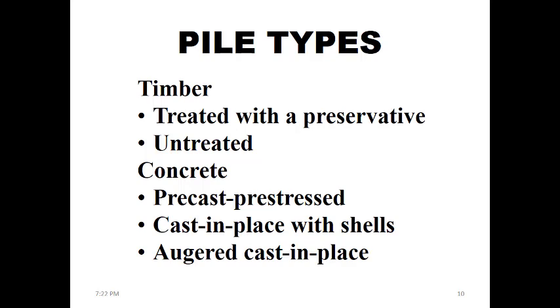If you think for a moment about the differences of a timber pile, why would someone go with untreated or with treated timber enriched with preservatives? The point is to increase the longevity of the pile itself, because timber is a natural product and over time it will degrade in quality because of many environmental effects and because of pests.